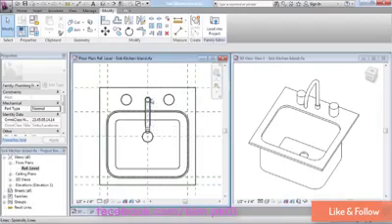So what they've done is the gray in the family editor represents a hidden element. And we talked about this briefly in a previous chapter, but there we used a visibility parameter. Here, the visibility is being applied a little differently. Here, the visibility is being applied as a view-specific setting.